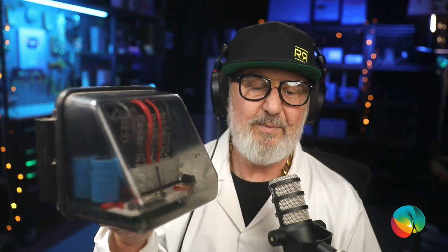So that means their VOC will be up around 18 volts or so. Around about 20, 21 volts. VMP around about 18 volts. And it meant charging a battery system. I had to series them up to approximate what the battery was. So it was a 24-volt battery system, so we tried to put 2 panels in series. But there was quite a lot of loss at that relatively low PV voltage.